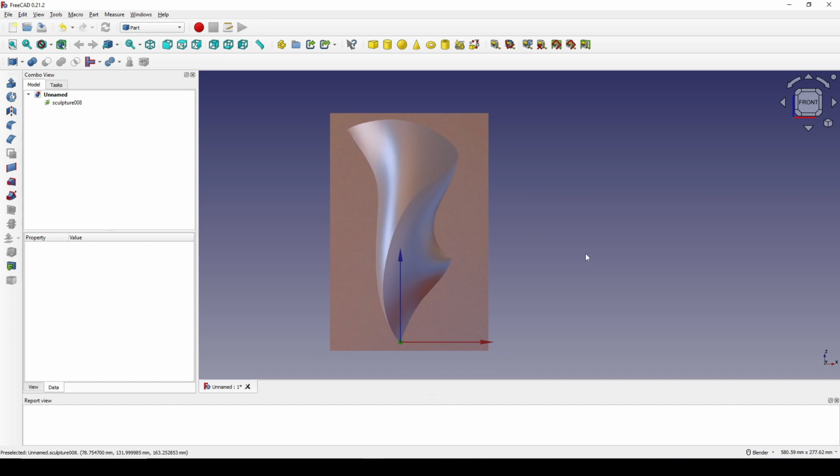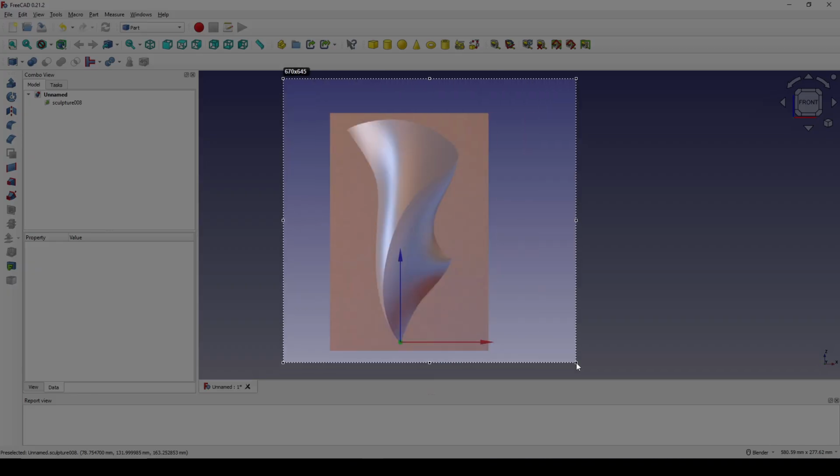In this tutorial, I will use the Freehand Bspline to create this curve over here, this curve over here, and this curve up here. And in this corner right here, I will use the plane curve in the surface workbench. After that, I will create another Freehand Bspline, connecting this point and then this point together to create the middle curve.